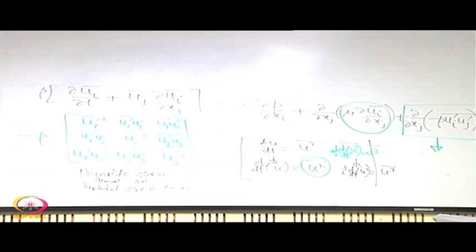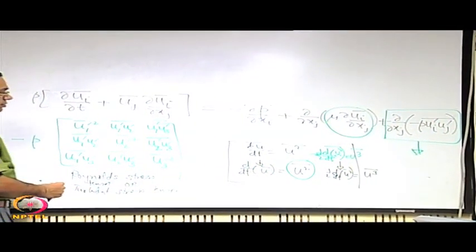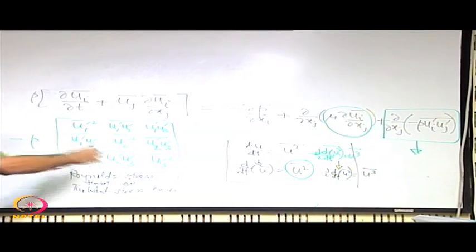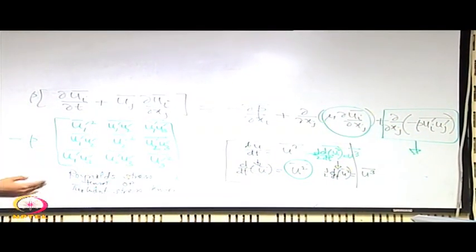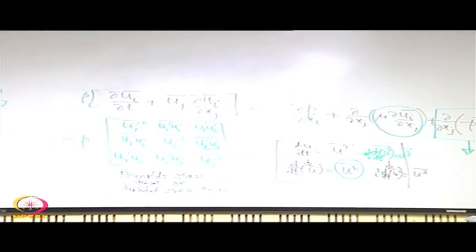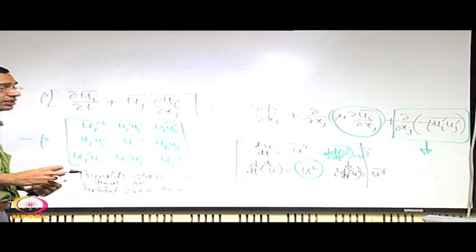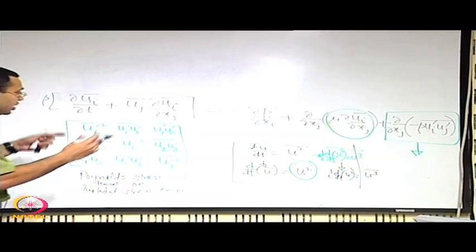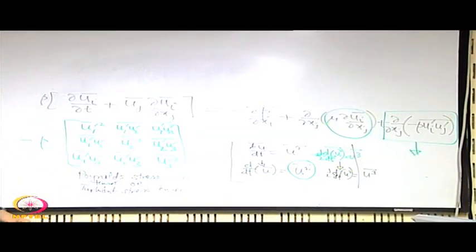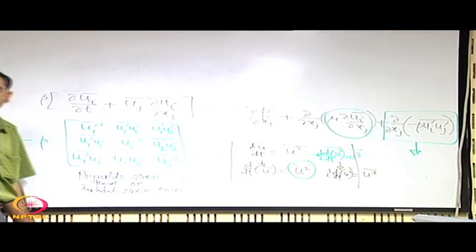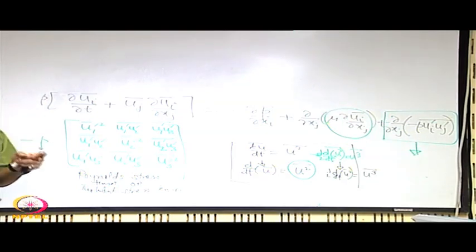So, if you recall, in our usual stress tensor we had the diagonal terms and off diagonal terms, and the diagonal terms were representative of the so called normal components and the off diagonal the shear components of the stress. And when we derive the constitutive relationships, we decompose the stress tensor into two parts. One is the hydrostatic component, which was obtained by sort of averaging the diagonal terms, and that was manifested in the form of a pressure which is acting equally from all directions, and a deviatoric component or the deviation from